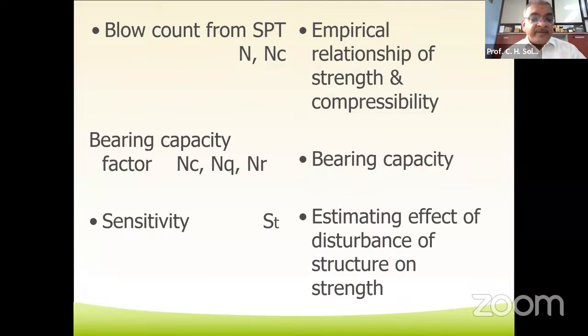Blow count of SPT, we have understood the significance of it and what the correlations are. The bearing capacity factors which are used in the equation of the bearing capacity are determined from the angle of internal friction phi. Various researchers have given these bearing capacity factors depending on the angle of internal friction phi. And what is sensitivity? Estimating the effect of the disturbance of the structure on the strength of the soil is known as the sensitivity.